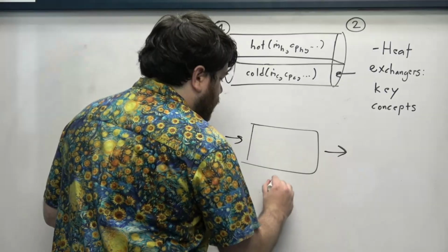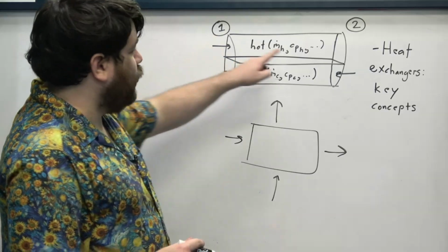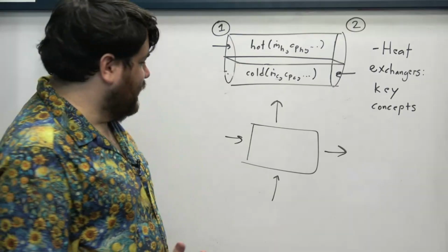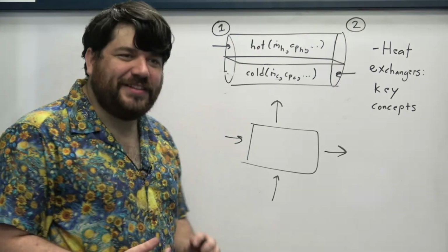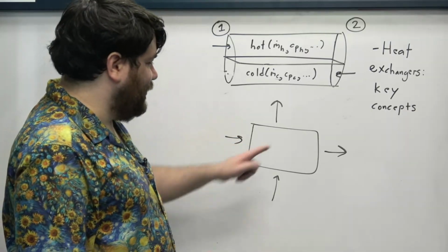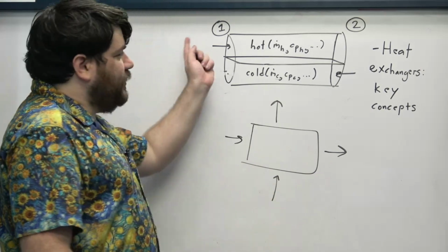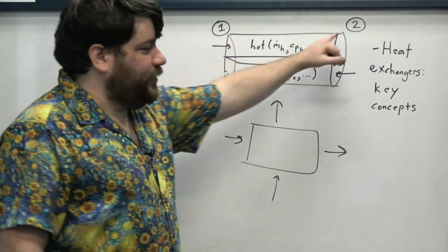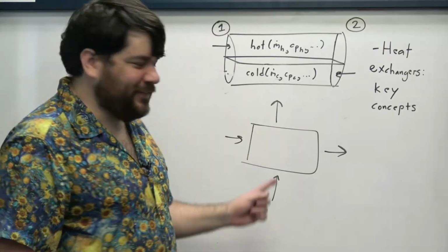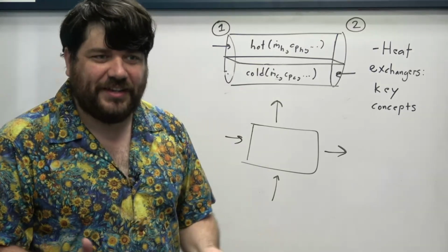right? So flow kind of looks like this for the two liquids. The idea of setting up a 1 and a 2 doesn't really work that much anymore, right? Because this is just an inlet for a cold liquid or a hot liquid. Like, this is just an inlet. This is just an outlet. This is just an outlet. This is just an inlet. So we don't really have the mechanism of just defining a 1 and a 2 over here and then saying, okay, how do we actually calculate these numbers? How do we calculate, for example, delta TLM?